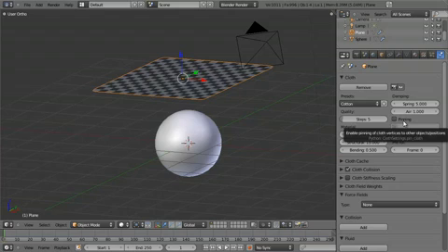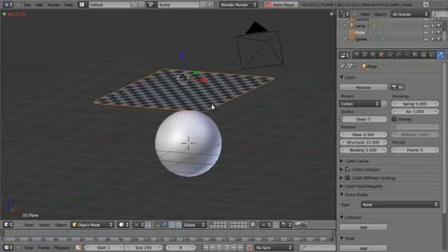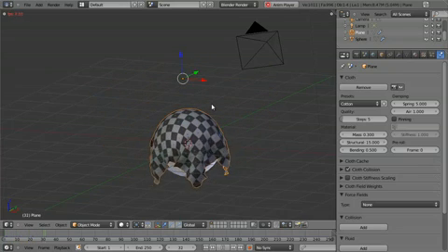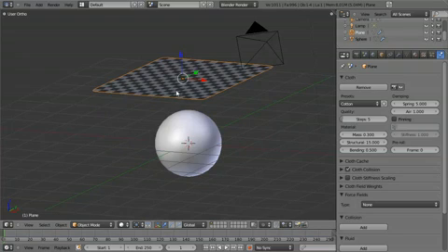Then our next thing is something that we're going to look at real quick here, and that is pinning. And what pinning does is allows us to basically define certain parts of the mesh that do not get collision or only partial collision. So for example, right here, it just drops completely. Well, what if we wanted to make something, say, like a window curtain? Well, currently, this wouldn't work very well. We could technically drape it over a pole, but then chances are, over enough time, it would just slide off the pole. So that's really not what we're looking for.